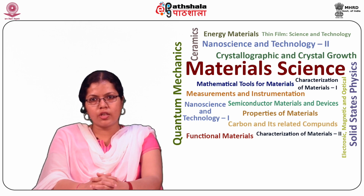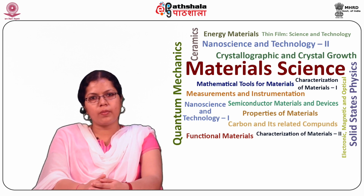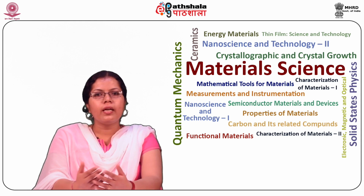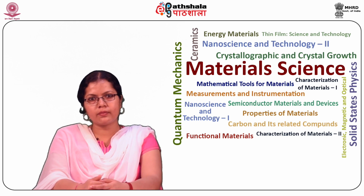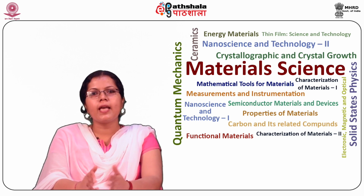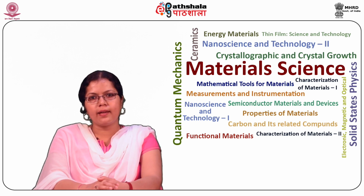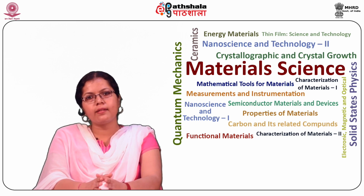When the current from the generator flows through the pressure coil, the coil tends to set itself at right angles to the field of the permanent magnet. With the test terminals open, corresponding to infinite resistance, no current flows through the deflecting coil. The pressure coil thus governs the motion of the moving element, causing it to move to its extreme counterclockwise position. The point on the scale indicated by the pointer under this condition is marked infinite resistance.